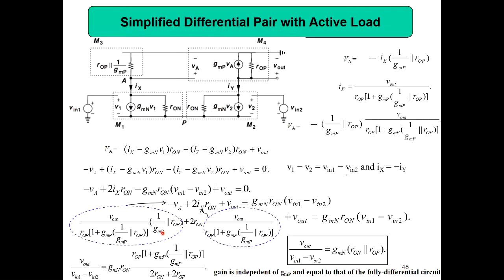So two things. When there is an asymmetry, the splitting is not very accurate, so we have to write down the entire small signal and then find out the gain. That is a more accurate way. But if the asymmetry is not very big, you can split it and find out, and you will get an equation close to the full small signal equation. You will be getting this extra term, which is very, very small. So approximately it is correct.